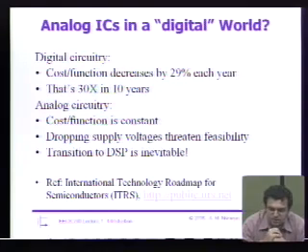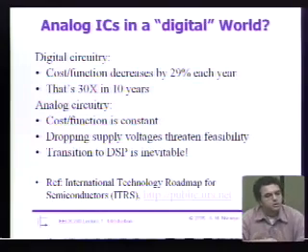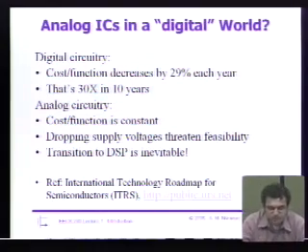So how does that compare with analog circuits? If you now go look through ISSCC past 10 years and you look at analog circuits, you realize that the same benefits don't apply to analog circuits. In fact, analog designers in many ways have been working really hard to deal with this constantly changing technology. For the digital guys, it's gotten better and better. For the analog guys, it's gotten harder and harder to build high precision amplifiers with lots of gain, with good matching, with good yield.